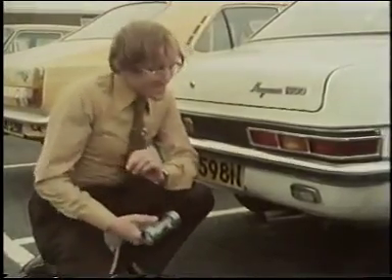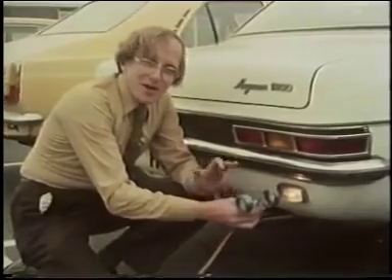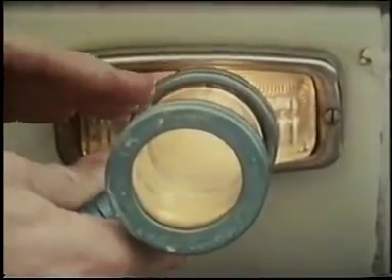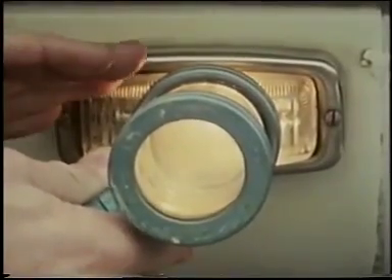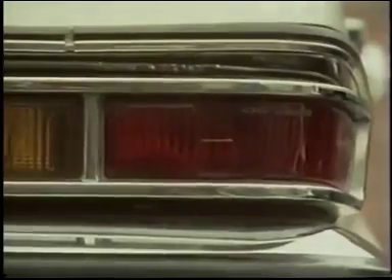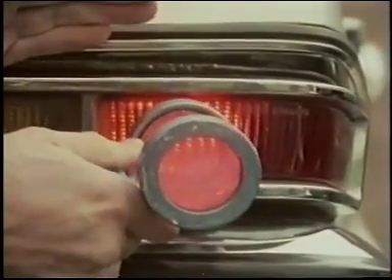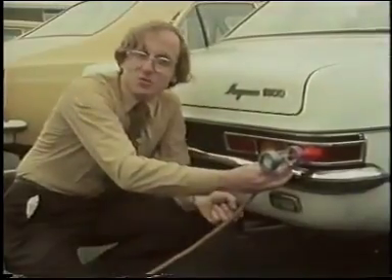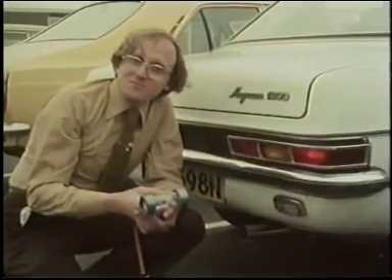What they do is they take a light source and shine it through the cell. Now, by measuring how much of the light is absorbed in the cell, they can work out what gases are present and in what proportion. In fact, if we just use white light, nothing much is absorbed. But what happens if we use red? Well, in this particular case, not much is absorbed either. In fact, to get a substantial absorption, we've got to go way beyond the red into the infrared region.